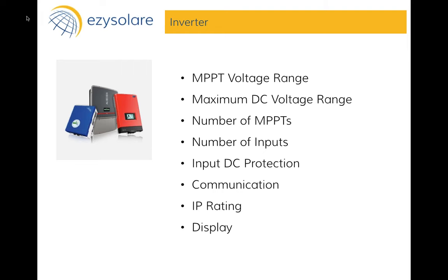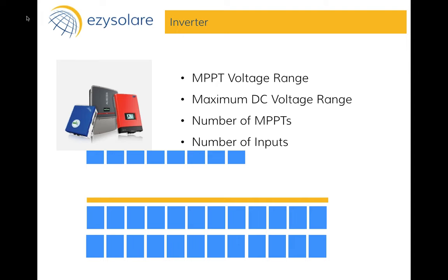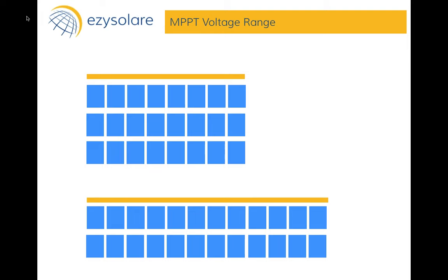Lastly, coming to PID losses, PID refers to potential induced degradation. Not getting into the technical aspects of it, what PID essentially means is that under some adverse weather conditions, the module starts degrading at an exponentially higher rate. When you have very high humidity and very high temperature, which is not too uncommon in Indian conditions, the panel output can degrade by as high as 40%. So ideally, if you can get anti-PID panels from panel suppliers, that is best. Otherwise, there are other modes of protecting yourself against PID losses, one of which is negative grounding protection in the inverters.